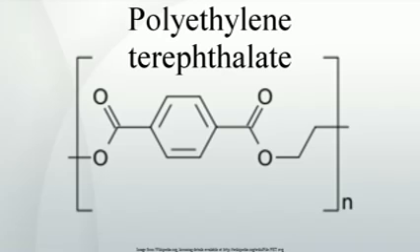For the adjustment of the necessary viscosity, besides an efficient drying of the flakes, it is possibly necessary to also reconstitute the viscosity through polycondensation in the melt phase or solid-state polycondensation of the flakes. The latest PET flake conversion processes are applying twin screw extruders, multi-screw extruders or multi-rotation systems and coincidental vacuum degassing to remove moisture and avoid flake pre-drying. These processes allow the conversion of undried PET flakes without substantial viscosity decrease caused by hydrolyses.